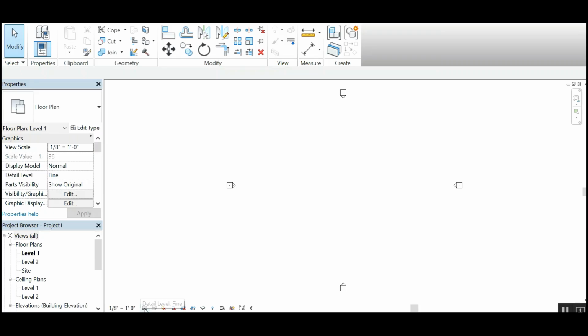If you set it for fine, now we'll see our little rectangle has kind of like a hatch pattern in it. That just means that the level of detail that we're seeing in this particular view shows absolutely everything that you want to see. If we were drawing walls in a plan view and we had the coarse setting set, we might see outlines representing the outside face and the interior face of the walls, and that might be it. When we set this for fine, it will turn on the various hatches for the various materials that comprise the wall. I like to see as much detail as I can, so in all my views I turn on the fine resolution.